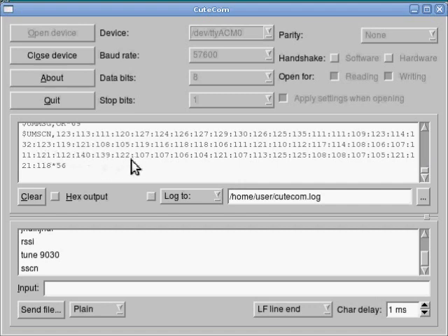I think this is coming from interference generated by something here in the lab. I've tried the same receiver on other computers in other places, and there is no spur there. So my PC happens to be sending out interference. It's not really loud interference, but it's there. So you may see different numbers here, and it's also possible that at the time we were scanning that particular frequency, there was actually data coming in from a utility meter transmitter.